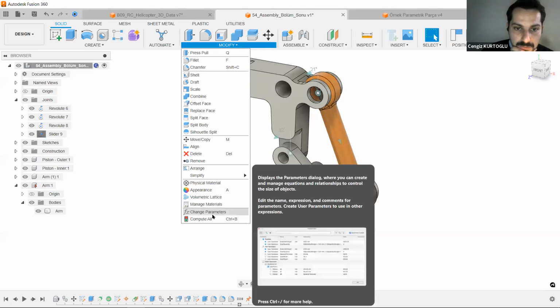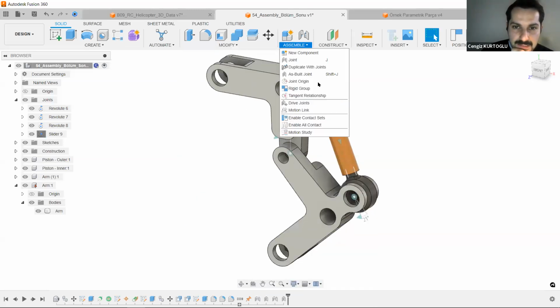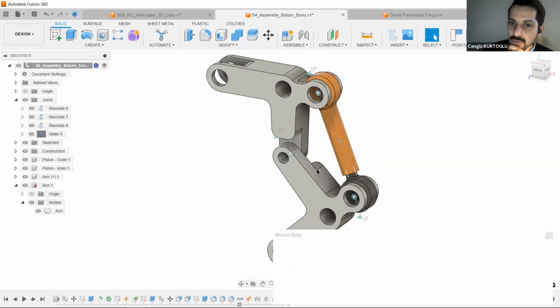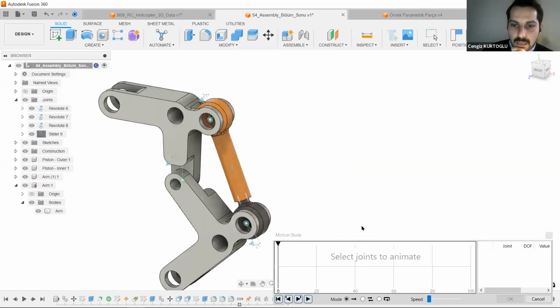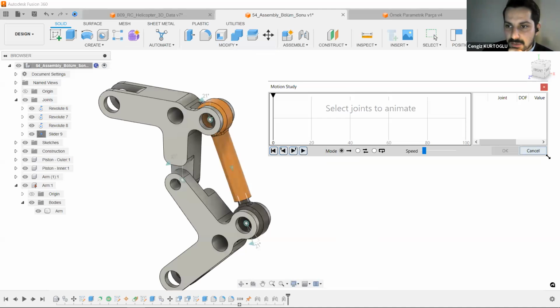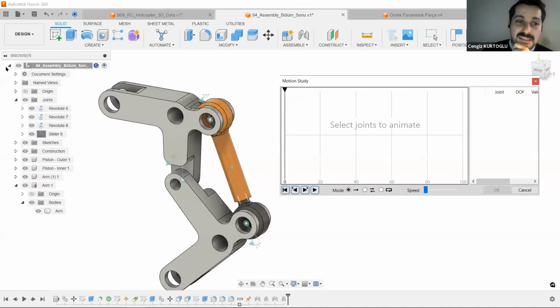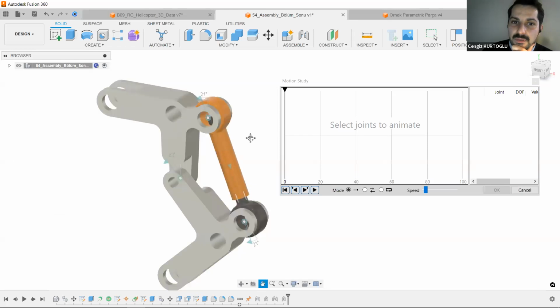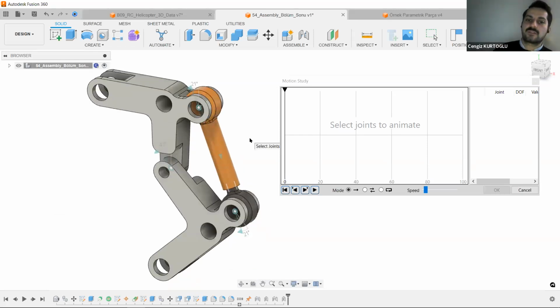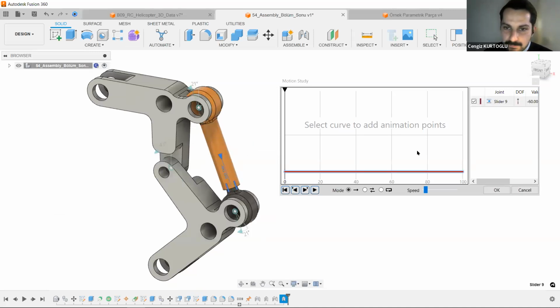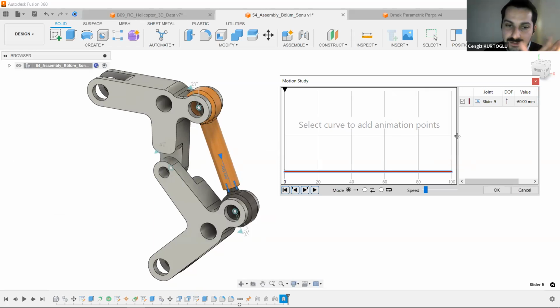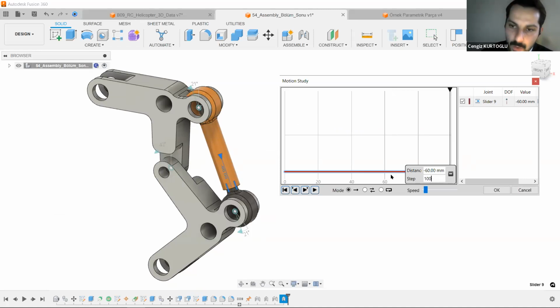You can check it out. You can assemble motion study for these parts. Well, on the first projects on the robotic arms, there are several different revolves that we have to add joints. But for these projects, it's not necessary to add other joints. It's just one joint as a slider joint, as a step 100 and distance 0.